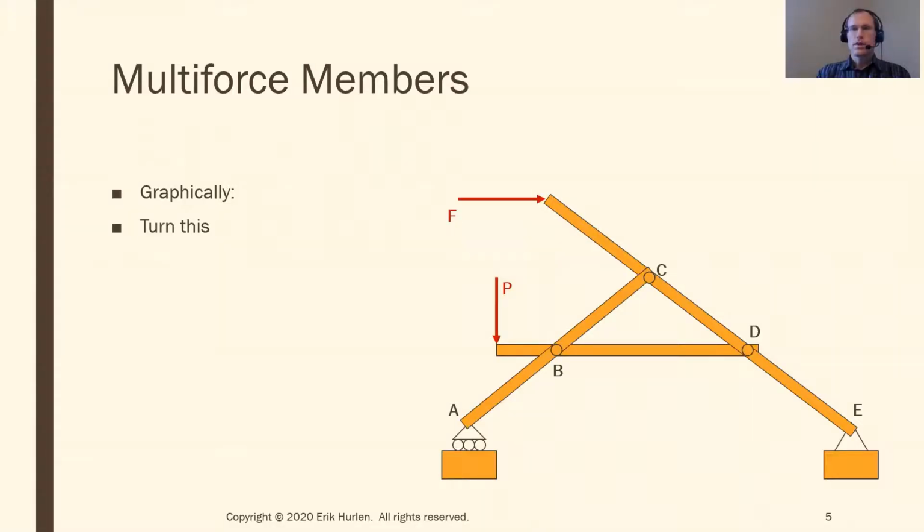And so one thing I want to emphasize here is that even though I'm talking about this force bending this member and that force bending that member, in terms of our statics analysis, we're still dealing with purely rigid bodies. So even though I'm saying that this is going to want to bend this thing, I'm still assuming that these things are completely rigid. These things are not going to bend. So again, the actual bending will be in one of your future classes. For now, we're still assuming everything's rigid and nothing is actually bending. But what we're concerned about now is the fact that these are now multi-force members. And so we want to know what those forces are inside of them.